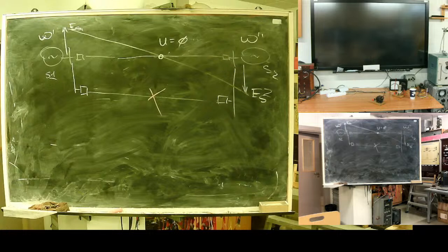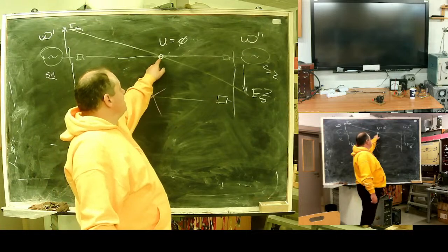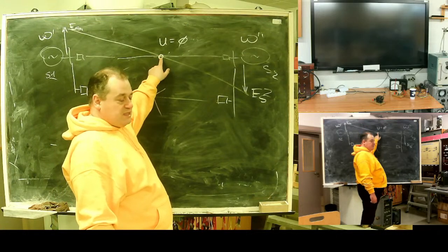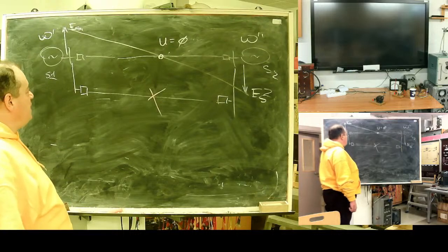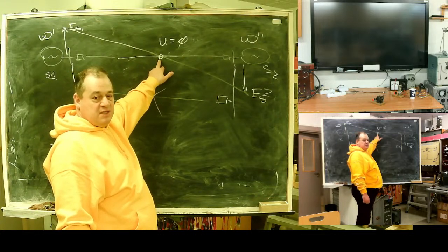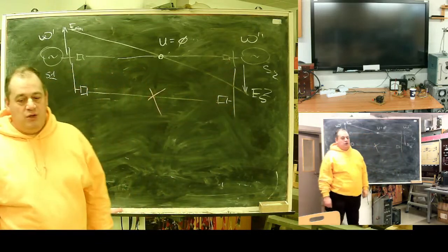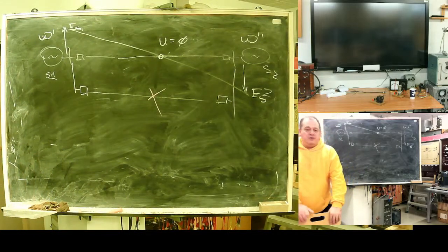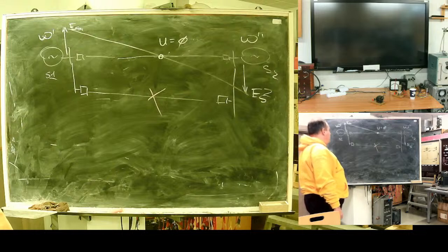At the moment when everything has gone badly, Houston, we got a problem. We will see this asynchronous regime, and in asynchronous regime, at the point of the center of swings, voltage will be 0. For distance protection, the swing mode will appear as a three-phase fault at the center of swing. And these two protections will operate. What will happen? The disaster will go further. We will lose connection.